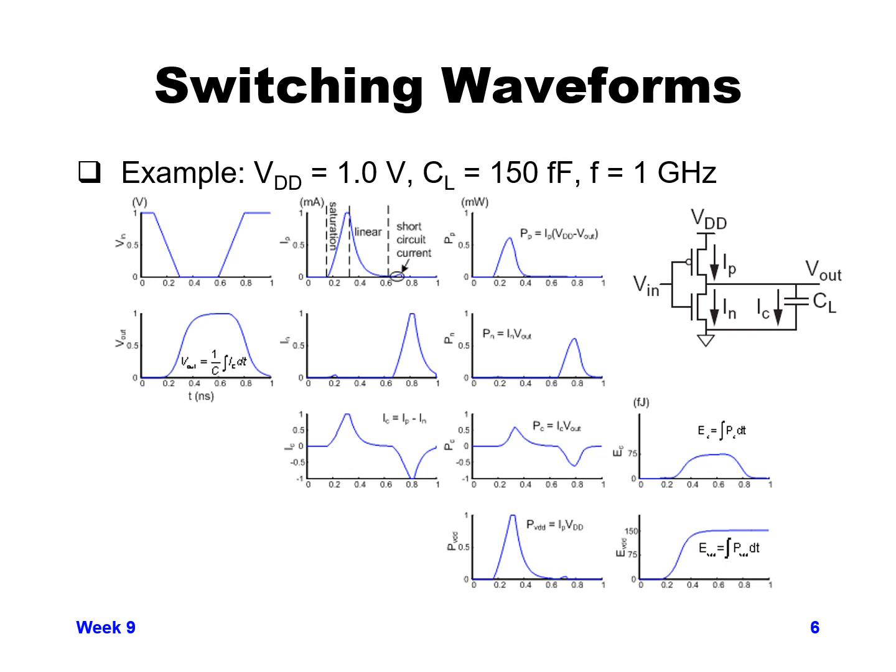Then finally, if we look at the power consumption, the power consumption through the PMOS follows the curve of the current through the PMOS. So you get a big spike right where the most current is through the PMOS. Similarly, for the NMOS, the second one from the top, you get a spike where the current through the NMOS is the largest. And then the power through the capacitor looks very much like the current through the capacitor curve.